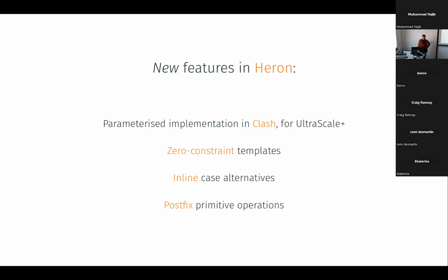Previously, there were a few different potential conflicts between subsequent cycles, and that was just very conservatively dealt with by a compiler pass. So you'd often be underutilizing the dimensions of your templates just to avoid these hazards you can have. We've moved all of that into the runtime. So very small additions to the circuits to detect that dynamically at runtime. So most of the time we've got better throughput. Occasionally we will have to stall.